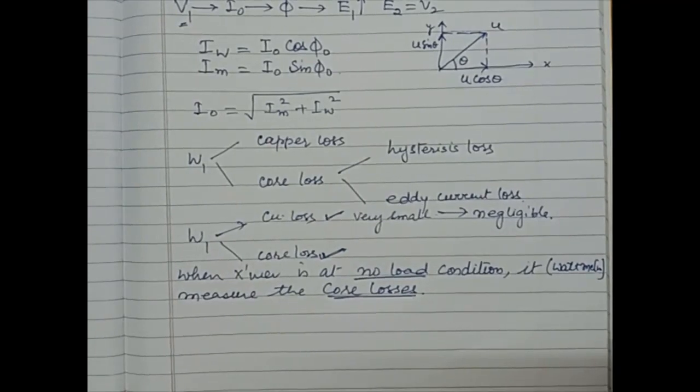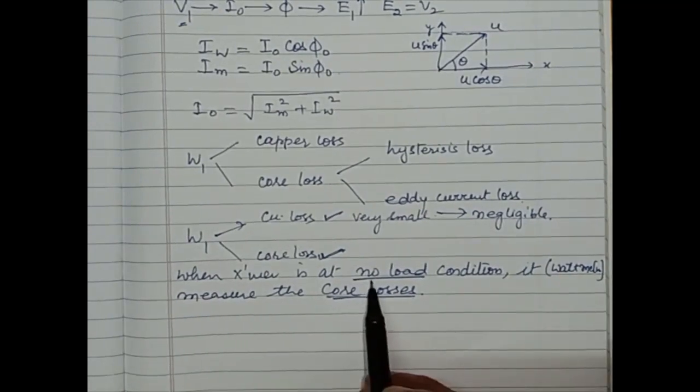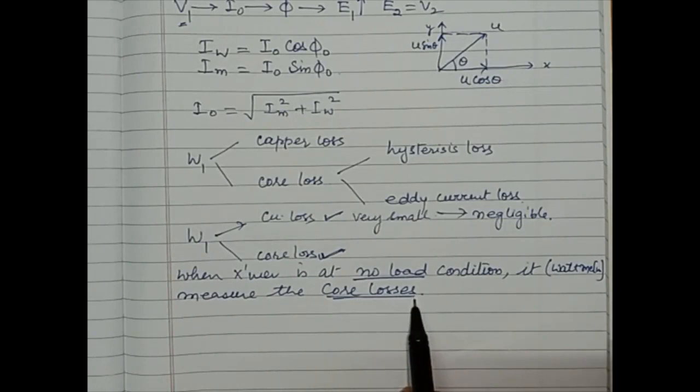Therefore, we can conclude what the significance is, or why it is necessary to study the transformer at no load. By studying the transformer at no load, we can find out the core losses produced in the transformer. Okay, thank you.